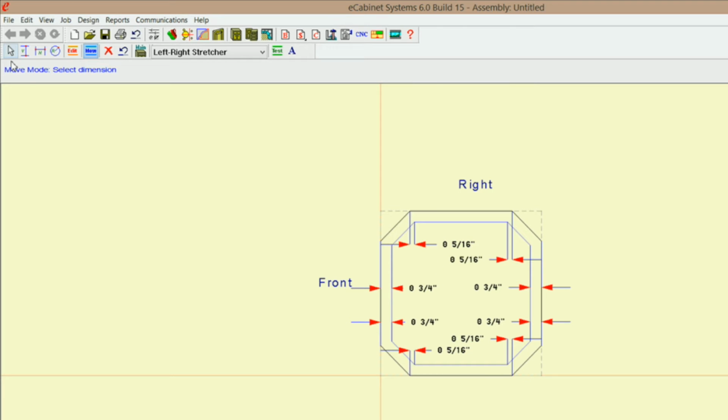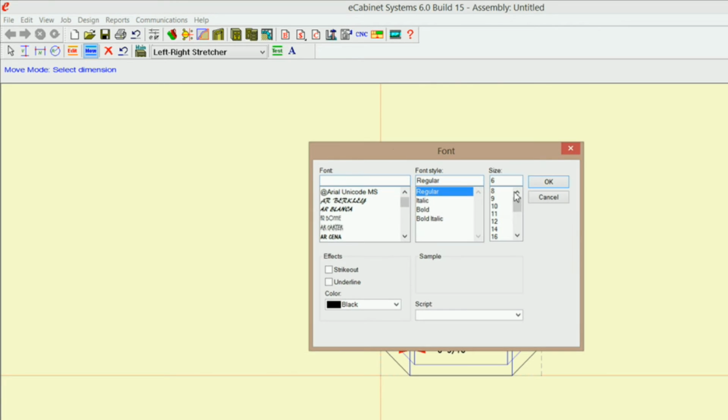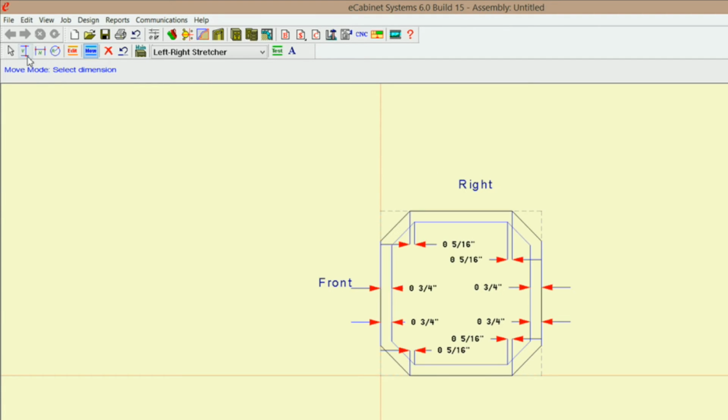Now we need to do our verticals. I'm going to change my font color just so I know, or I can keep everything separated. So I'm on a black here. Let's go to blue. I'm going to click OK. Now we need to do our verticals on these. So I'm going to click on the same corners. The only difference is we're doing vertical constraints. And we need vertical and horizontal.